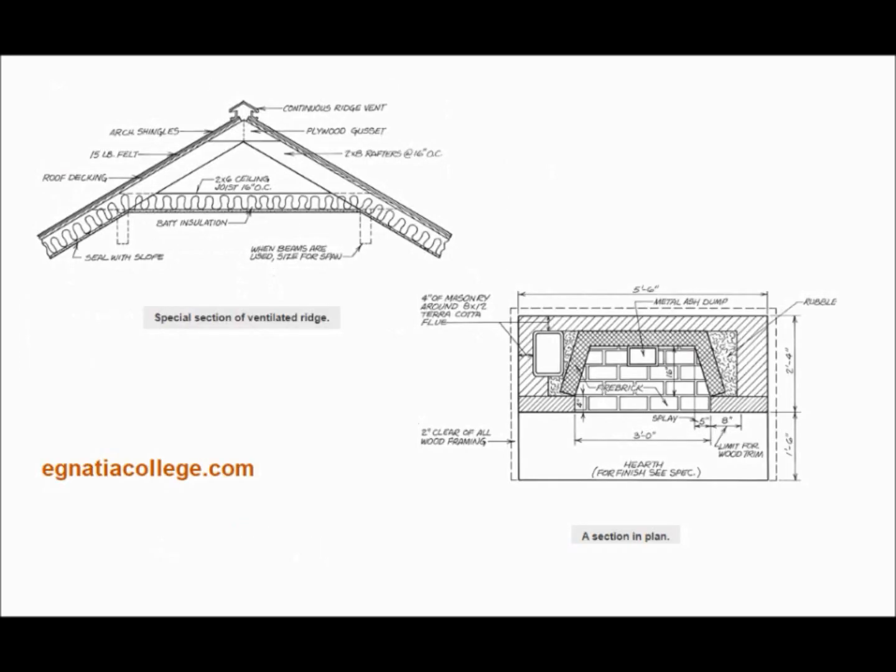Full sections and wall sections normally have only a few dimensions, but have many notes with leaders to identify the parts of the wall. The following is a list of the kinds of information that are included on typical wall sections with most sets of drawings. Footing size and material. This is specified by building codes. Foundation wall thickness, height, and material. Insulation, waterproofing, and interior finish for foundation walls. Fill and waterproofing under concrete floors. Concrete floor thickness, material, and reinforcement.